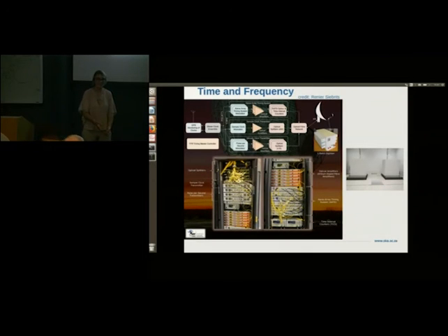Paul, you had a question? Yeah, the beamformer correlator, you mentioned FPGAs, are you also using any CPU or GPUs? So the MeerKAT correlator beamformer doesn't specifically make use of CPUs or GPUs. That is all SKARAB based, which is FPGA based. And it internally has a MicroBlaze CPU for control, which is called a soft core. Does that answer? Yeah. Cool.